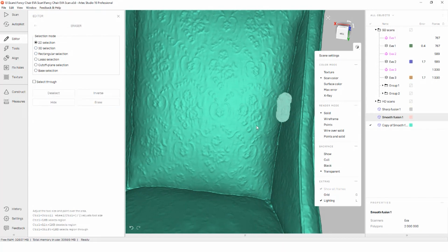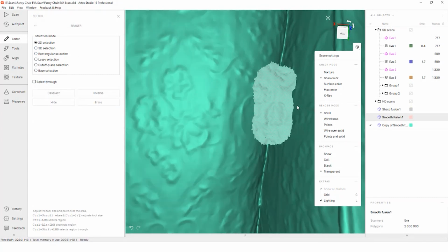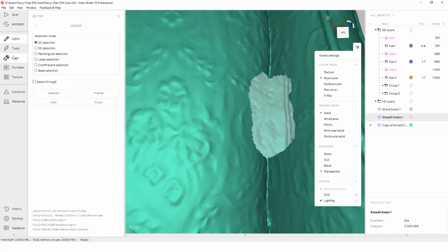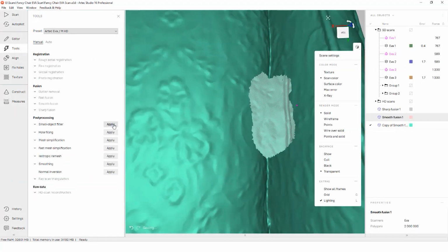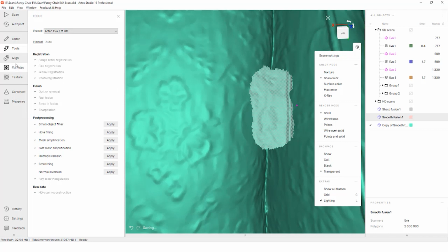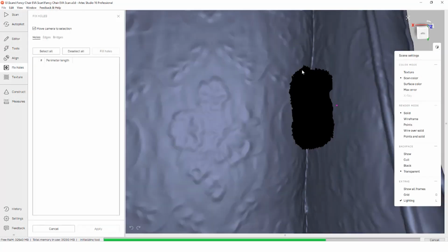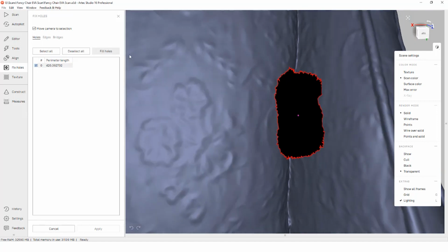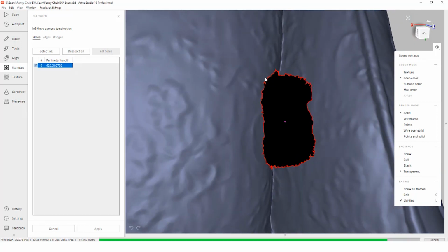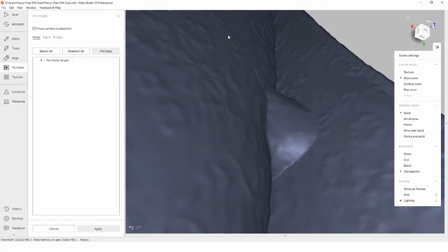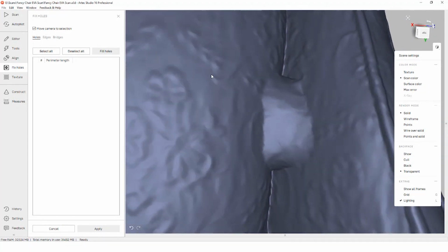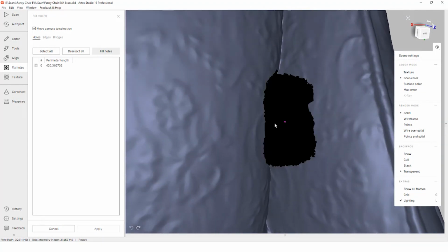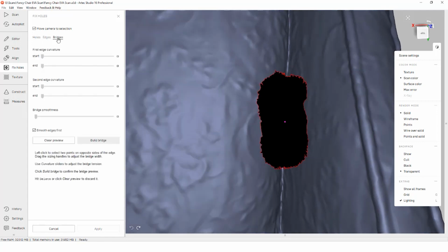To show off the Fix Holes tab, I'm going to first make a hole in the mesh. When we go into the tab, it will create a list of all of the holes within our mesh. Since I processed this with watertight, only the hole I made will be visible. If we select the hole and click Fix Hole, it will do a shortest path hole fill, which may be good for flat surfaces, but not so well for corners or circles. For areas like this, we will need to break it into smaller sections. That will make the hole filling easier.